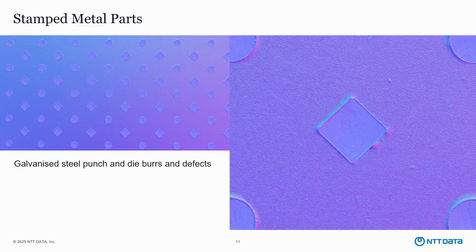they exceed tolerance, you know it's time to perform some maintenance on the punch and die or swap the punch and die out for a new one. And this means you're not producing parts and taking them through your process, because this is probably combined with many other parts to make a final product. And this means you're intercepting those problems right at the point of manufacture.